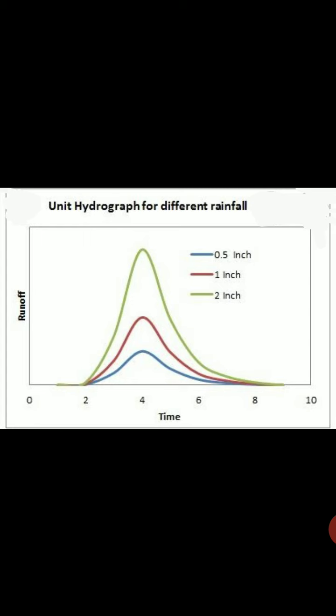For example, if a unit hydrograph results from a rainfall of 3 hours unit duration, it is known as a 3-hour unit hydrograph, meaning thereby a hydrograph produced by surface runoff from a storm lasting for 3 hours and yielding a rainfall excess of 1 centimeter.